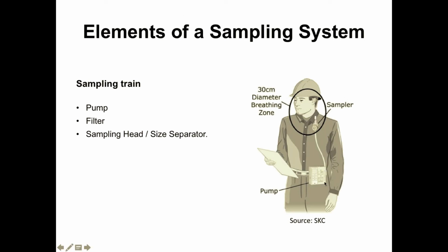It's going to be mounted on his belt. These pumps may be such that you just start them and they start running. They may be programmable so that there's a delay before they start running, run for a certain period of time and then shut off, and so on and so forth. Depending on what his work activities are and what the nature of the exposure is, you may be monitoring continuously over a whole 8-hour period. You may have this device running so that you either manually or automatically only sample during certain periods of time.